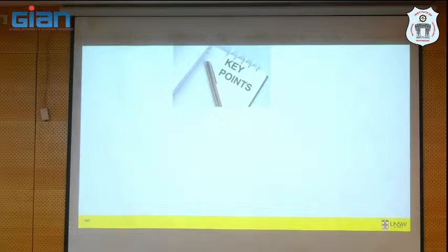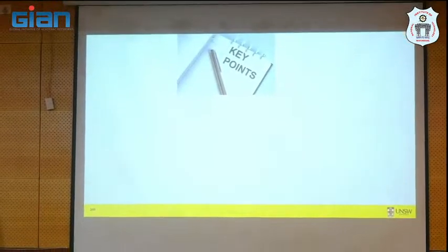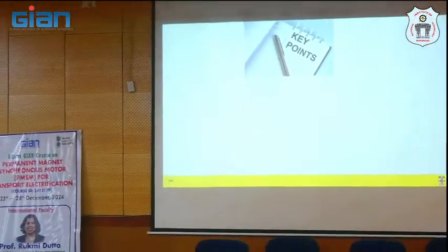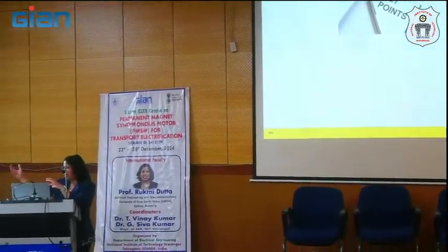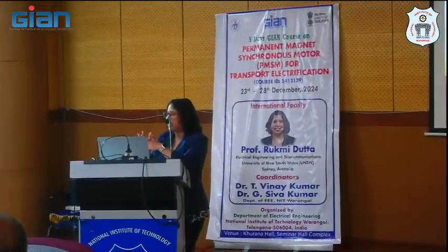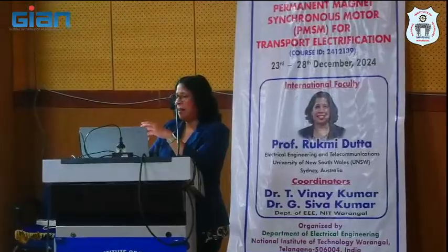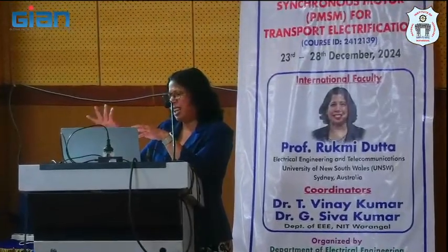But the encoder is kind of a mechanical device, right? So they need to also be robust enough to go to 100,000 RPM. So there's no such encoder. So we could not use the encoder for the high speed. So we bought one. It could work up to I think 40,000 or 30,000 or something.